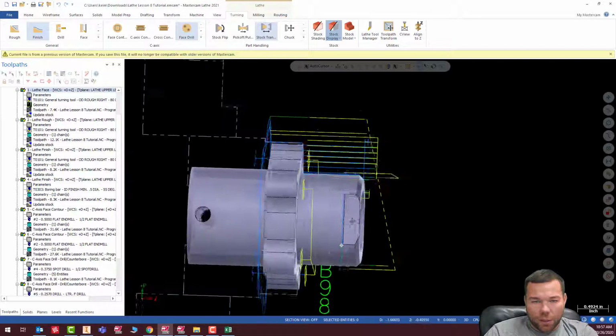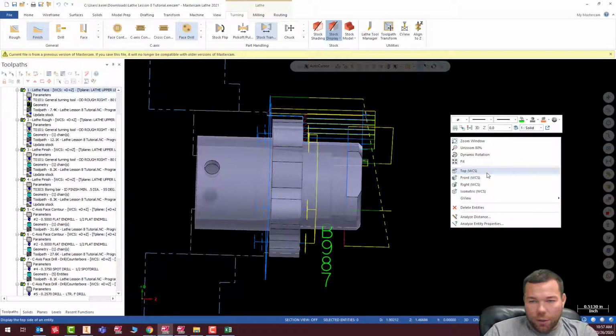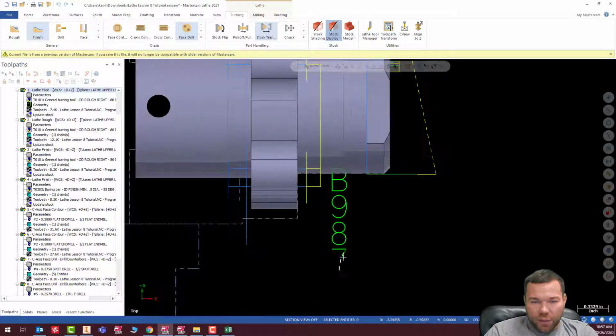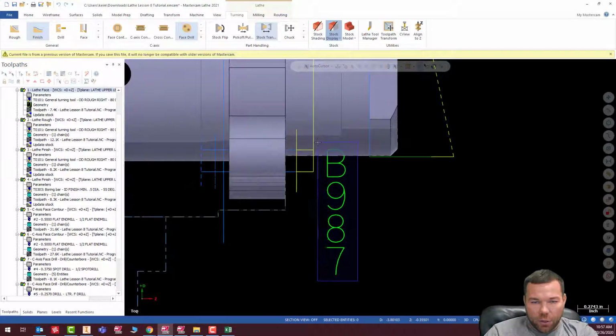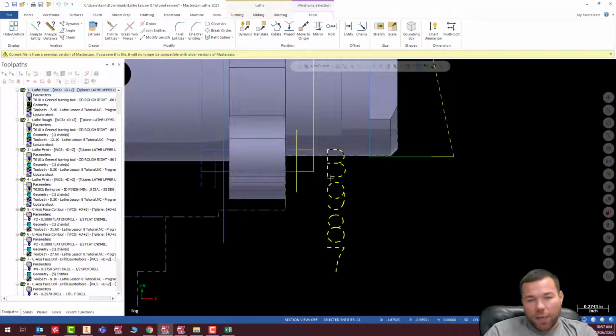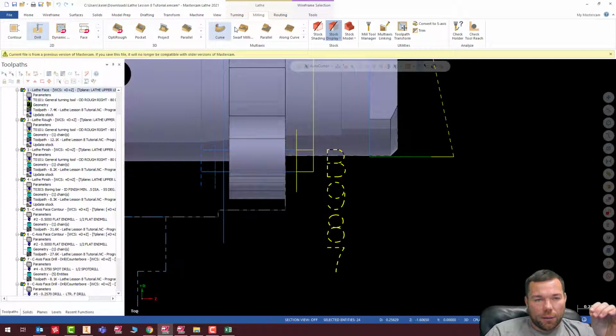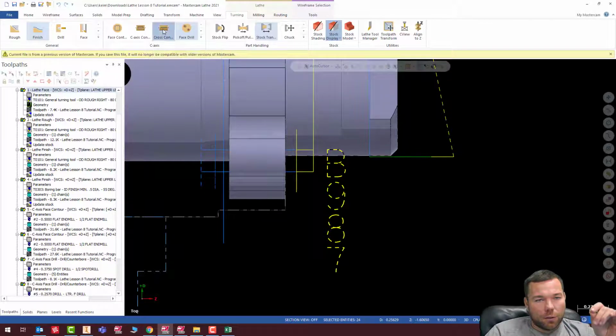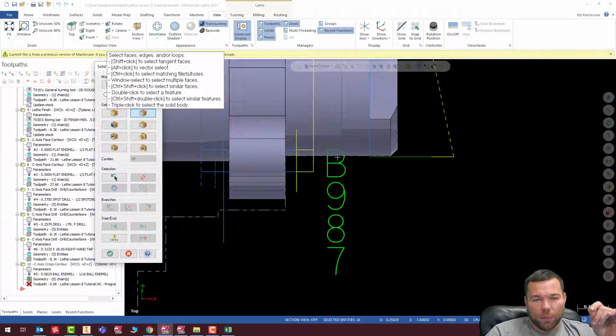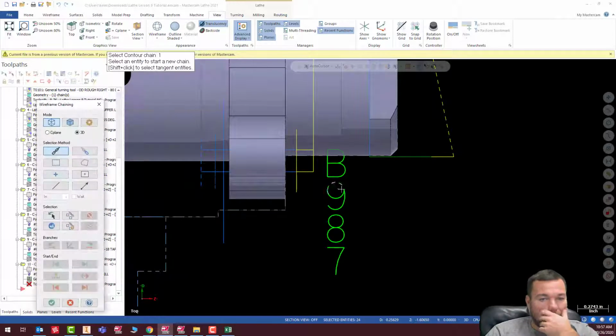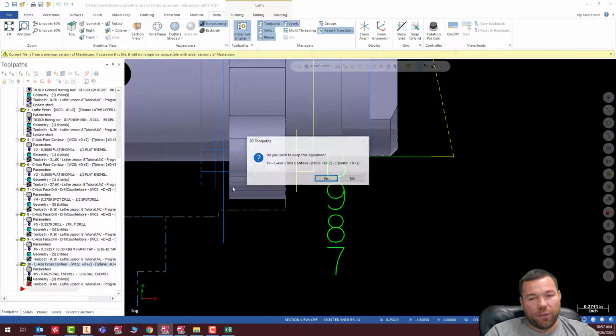And let's go ahead and take care of that. Now, as I stated in some of our classroom sessions, I don't like to just use a C-axis cross contour to do these. It's not really the way I like to do it. I could select this and run through that. I like to actually wrap the text around so I can control the orientation of the text. So that's what I'm going to do.